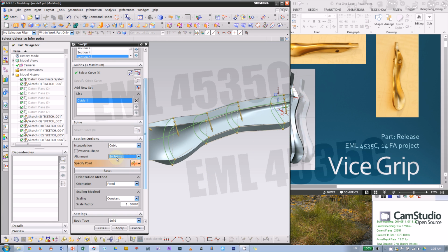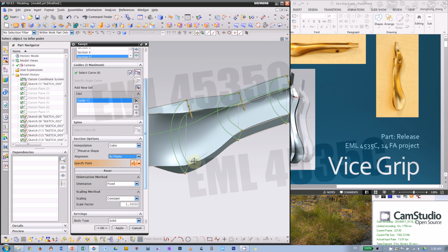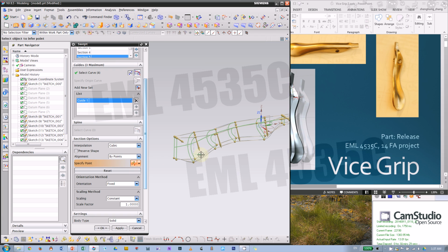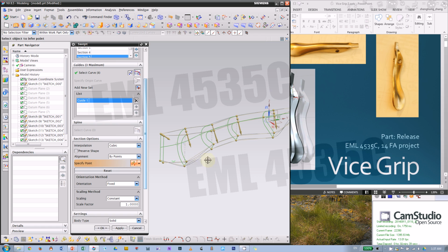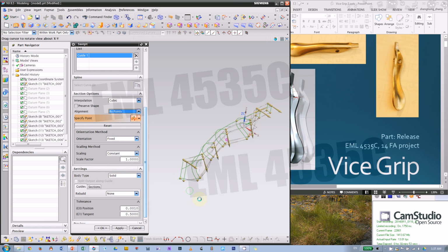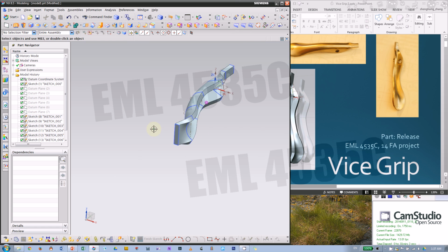Okay. And in this bipoints, you can actually align different points. So if I hover here, you can see those points are aligned to each other. If I hover here, right? So from this picture, you can also tell how swept works. It'll actually scan the same point on different cross sections along the path. So that's good for this part. Just click OK, and that's smooth. And next I'm gonna use edge blend to make this tail round into the geometry.